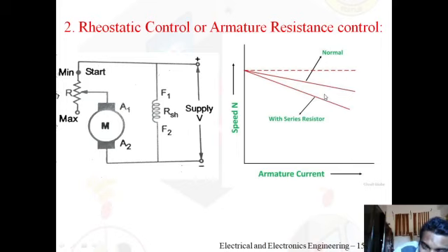The speed regulation increases because of adding resistance. Earlier only the IaRa drop came into the picture, but here the difference is IaRa plus the Ia R drop, which is due to the resistance added in series. Whenever the drop takes place, the armature voltage decreases. That one we have seen in the previous graph.